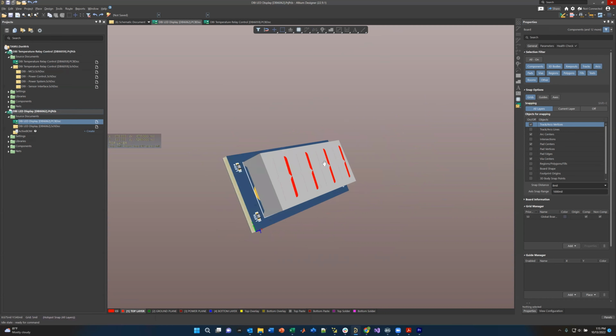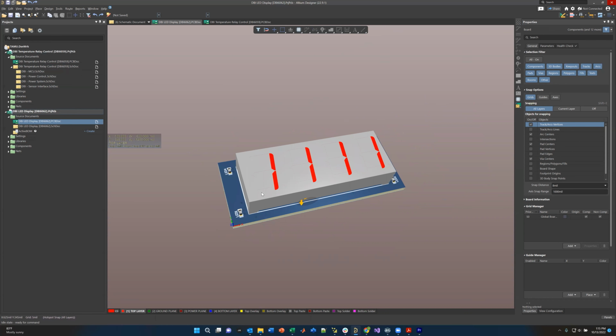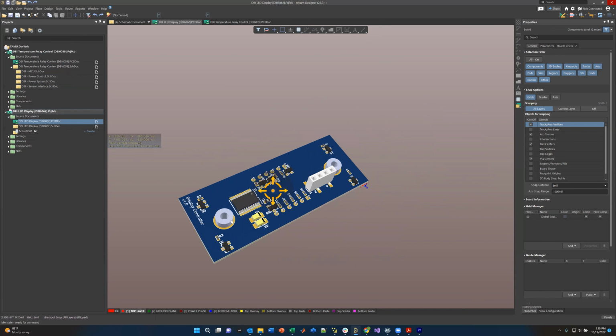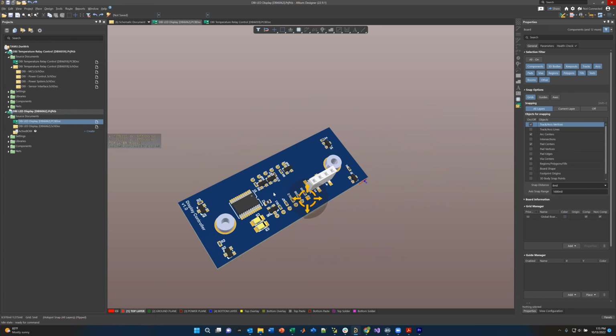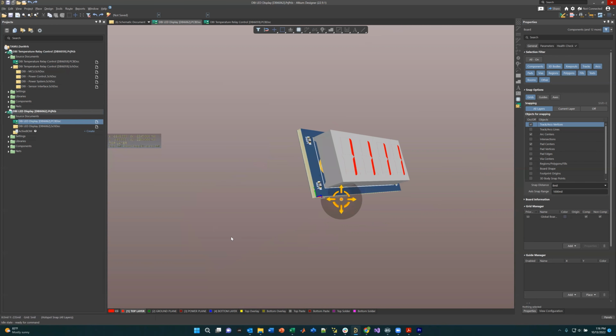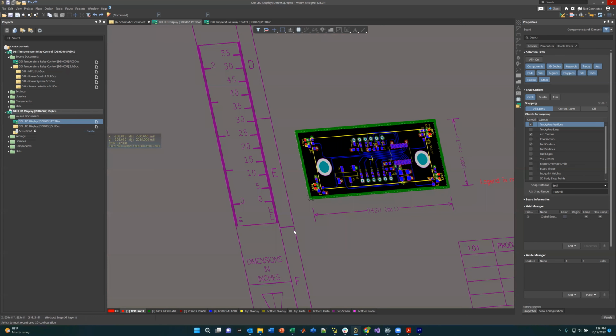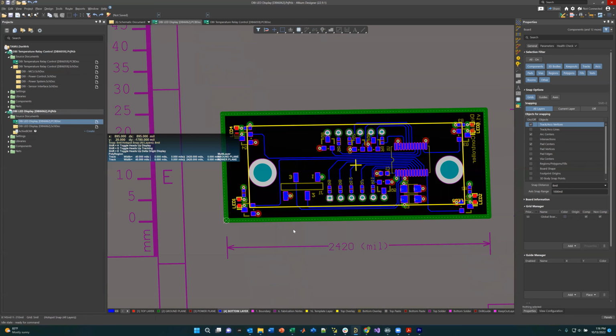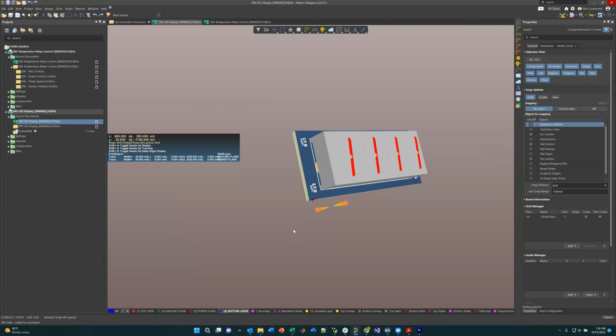I don't want any other parts on here because this is on one side. So all the parts went on the bottom side of the board, including these 2 standoffs I was talking about earlier. Here's the connector, here's the port expander, and here are all the transistors we looked at a moment ago. So let's go ahead and take a look at this layout. Put it back in 2D. If you use Altium, you switch back and forth with the number 2 and number 3 key, 2 for 2D view, 3 for 3D view, 2, 3, 2, 3. Pretty basic.